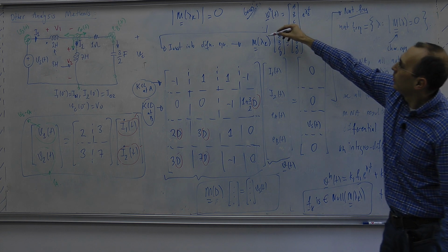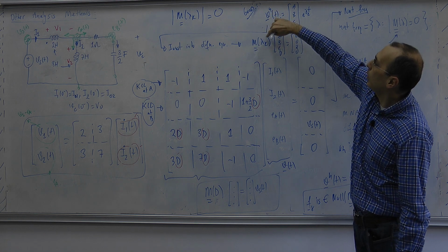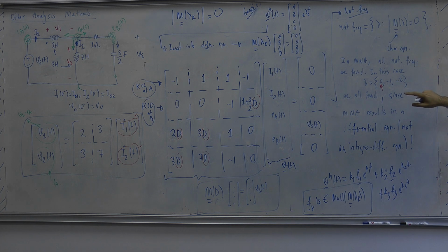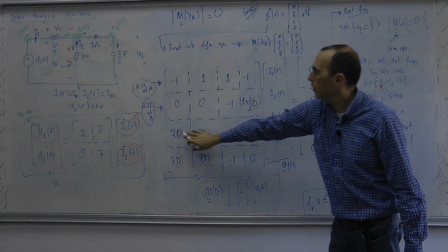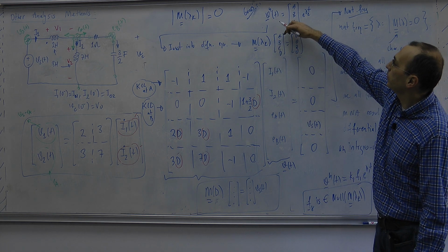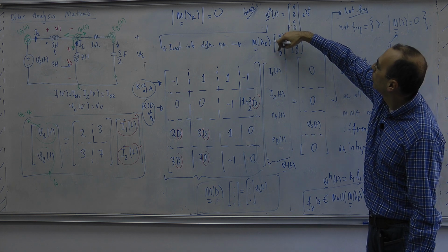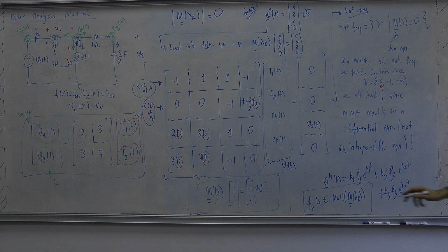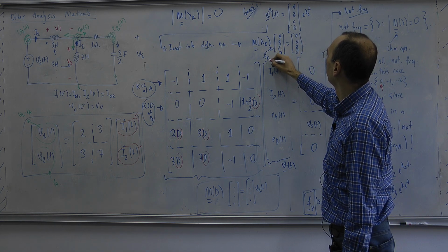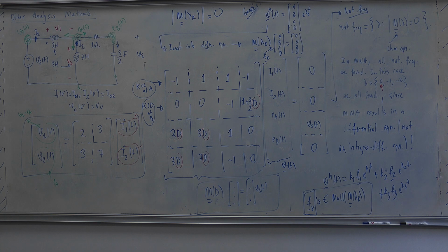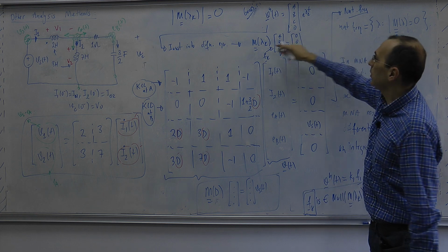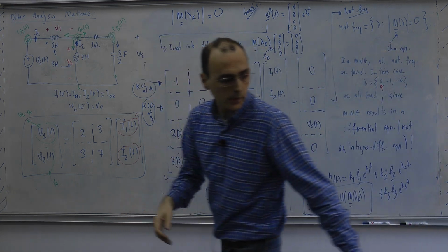But what we see is that now this is a singular matrix for a specific lambda k value, one of these natural frequencies, making this matrix, when substituted by lambda k's, singular, meaning that there is a non-trivial null space. So I'm talking about this a, b, c, d vector, which is this fk vector over here. In the state equation, this M matrix becomes lambda k times identity minus A. In the state equation, let me say it, and we are done.